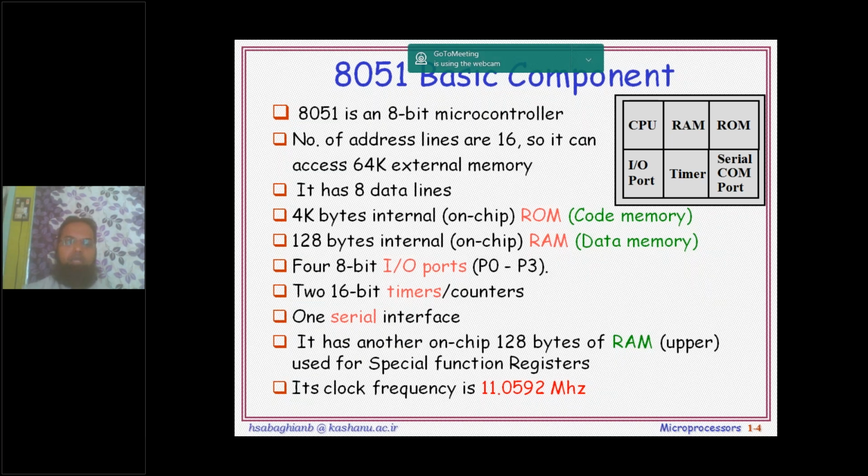So the microcontrollers, 8051 or PIC microcontrollers, follow memory mapped IO. So that's why all the registers are not registers in the physical sense, they are basically memory locations. So each and every register available in the 8051 microcontroller has an address.